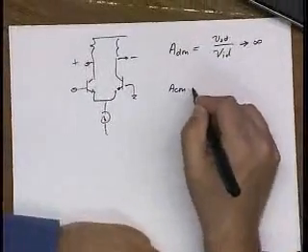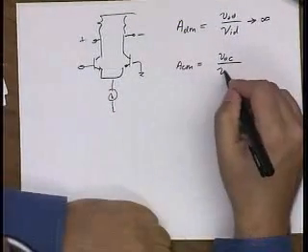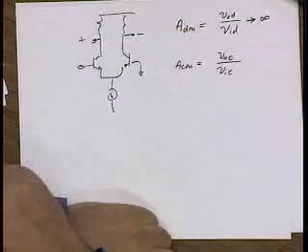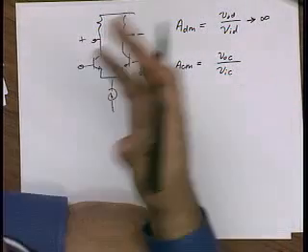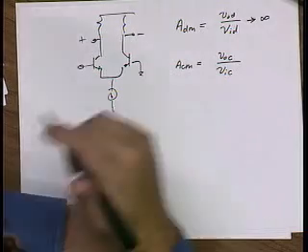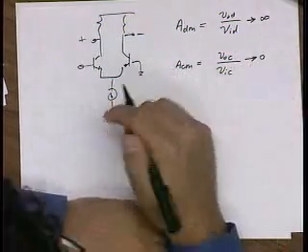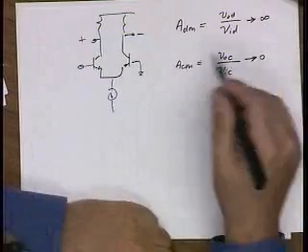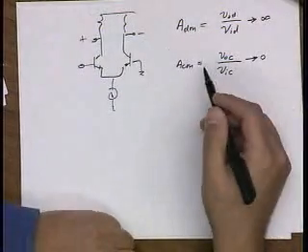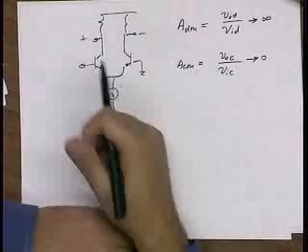Okay. What about the common mode gain? This is the common mode output voltage when you put in a common mode input voltage. Okay? And of course, we'd like to completely reject common mode signals, and so we'd like this to be 0. Actually, I don't care too much about this, because I'm building differential circuits, so I already know my common mode is going to get rejected.